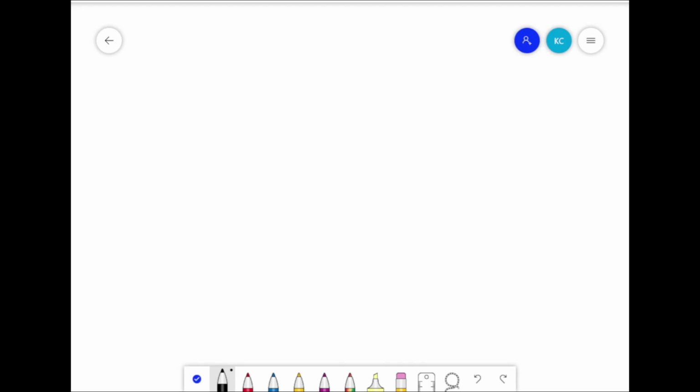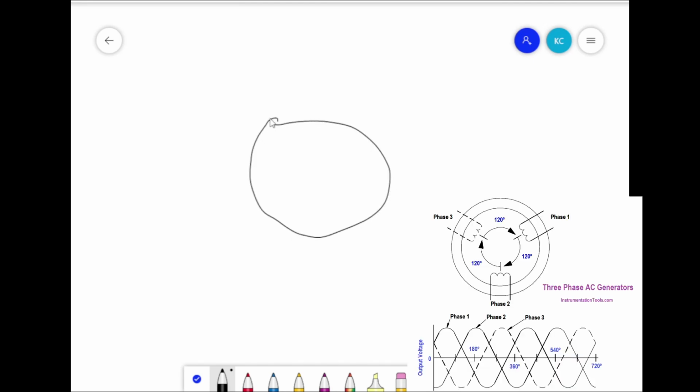Three-phase power, and why? I guess the short answer is that it was just the physical arrangement of generators back in the day. To visually illustrate this, there's a coil, and we'll have a permanent magnet that'll spin around like this. Basically the coils were just physically 120 degrees apart. So that's about here, and the other one here.